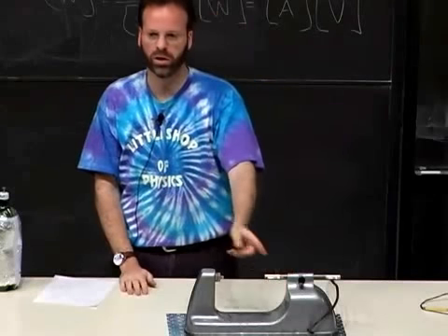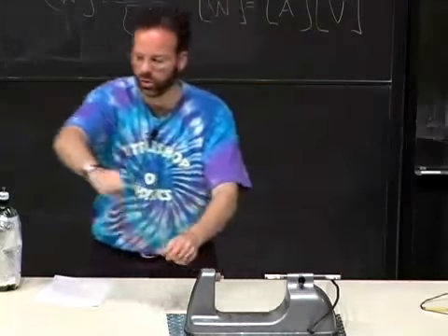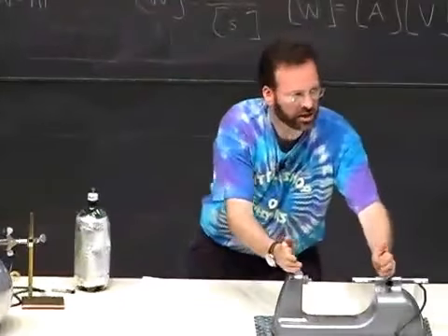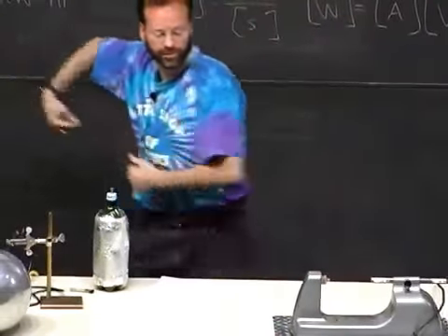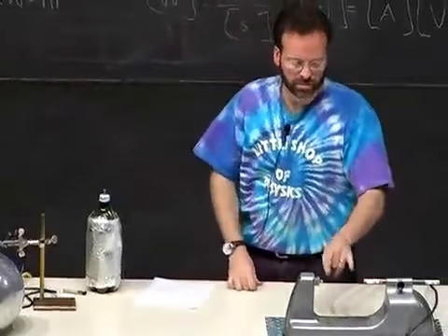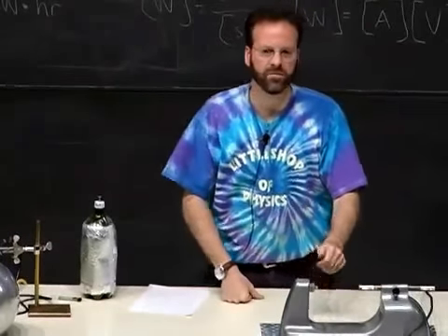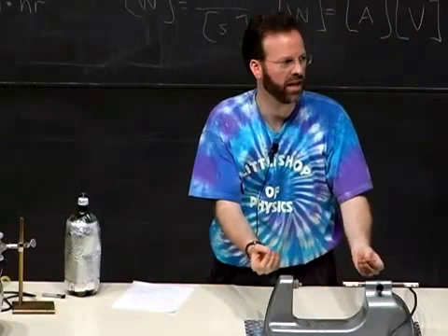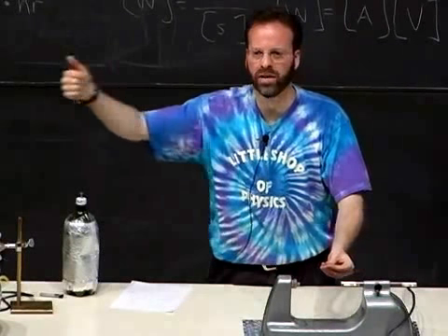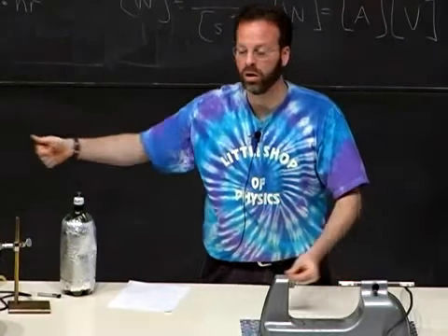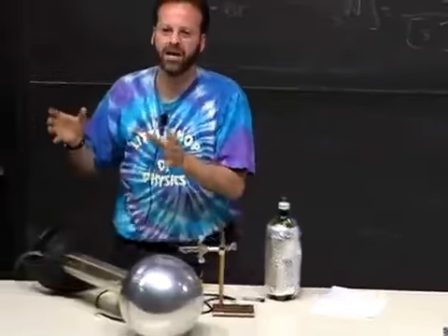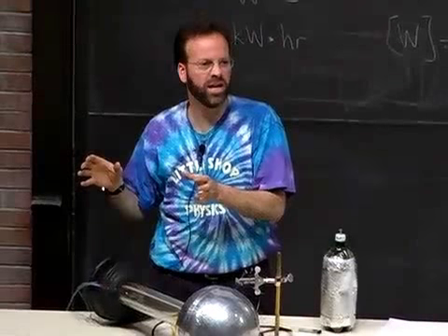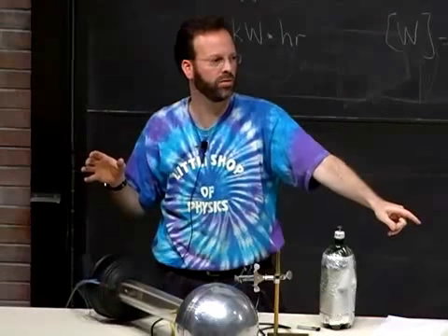And this is how fuses work. If you put this in series with your appliances, the same current flows through this as flows through your appliances in series. And if this burns at 10 amps, let's say if 10 amps or more flow through this and it breaks, it can't handle that, then do you get power to your appliances? No. So if your appliance will fry with more than 10 amps, you want to keep the current under 10 amps. You put in a fuse rated at 10 amps.